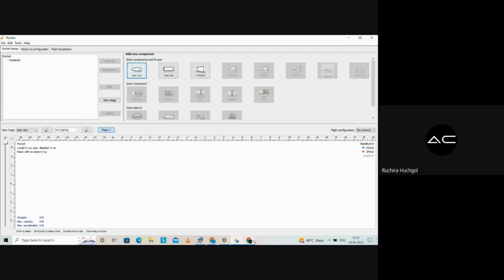So the tip of the fin plays a very major role, because when we talk about wings, we talk about airfoil, right? Similarly, when we talk about fins, we also talk about airfoil. The more effective an airfoil you have, the more effective your fins will be. So in a generic way, if we just talk about the shapes, elliptical are the most efficient.